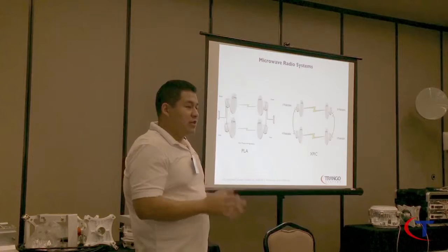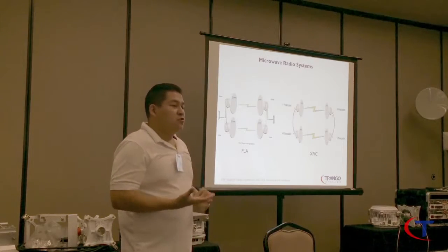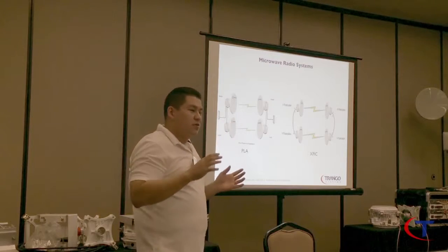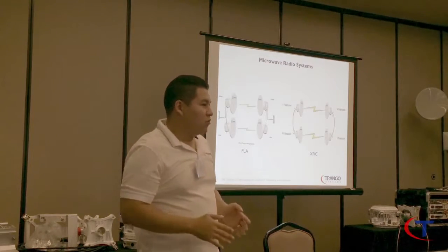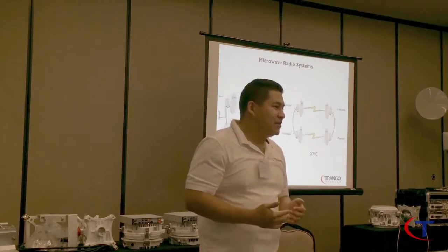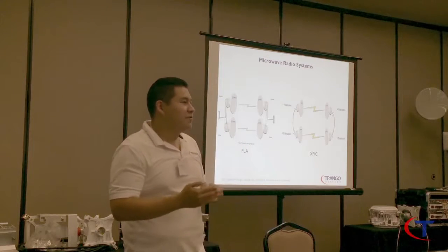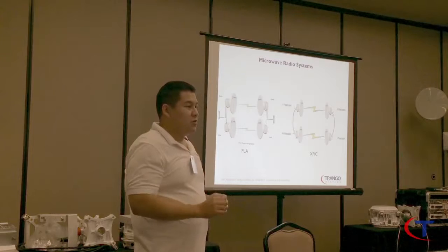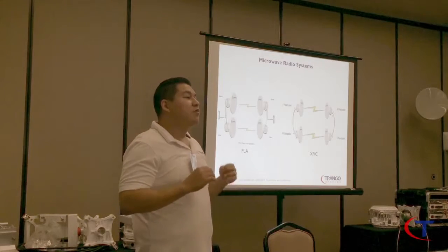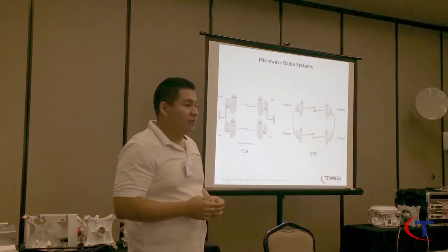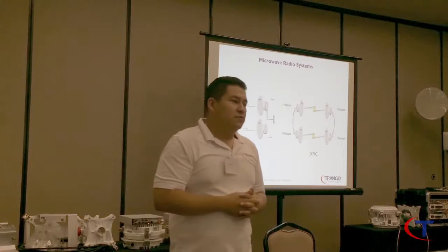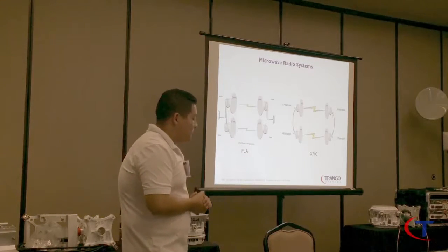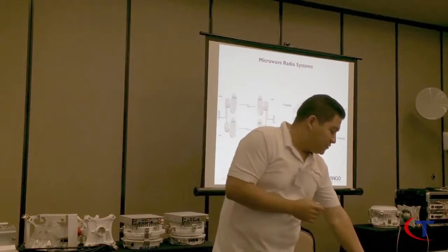It's cross-polarization interference cancellation. If you light them up next to each other, what's going to happen to the MSE? It's going to go really low. You're going to get 15, 10 MSE, because you have self-interference at that point. When you enable the XPIC feature on the radios, the MSE values symmetrically come up to the same value, either in the 30s or 20s, depending on the actual link. Any questions on the setups on the links?